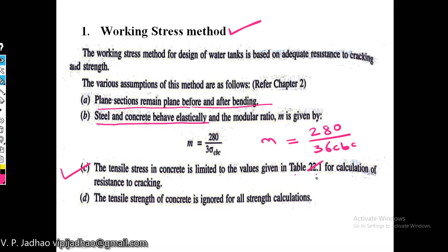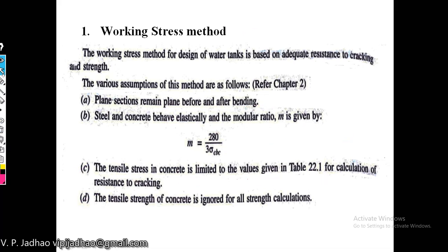table number 1, IS 3370 part 2. And the tensile strength of concrete is ignored for all strength calculations. So these are the different assumptions for the design of a water tank using the working stress method.